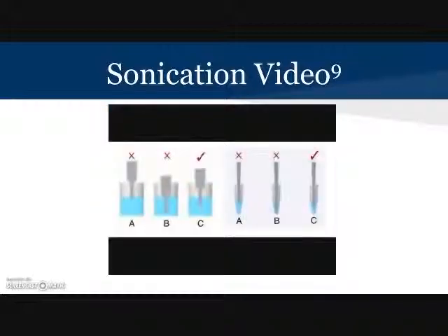Probe tips must be submerged properly. If the tip is not submerged enough, the sample will foam or bubble. If the tip is too deep, it will not circulate the sample effectively. Both conditions will end up with poor results.